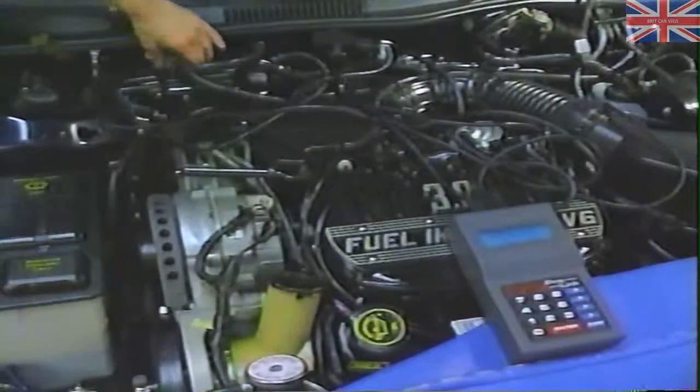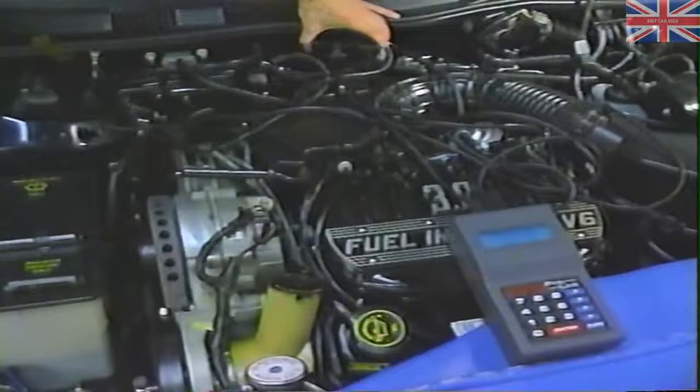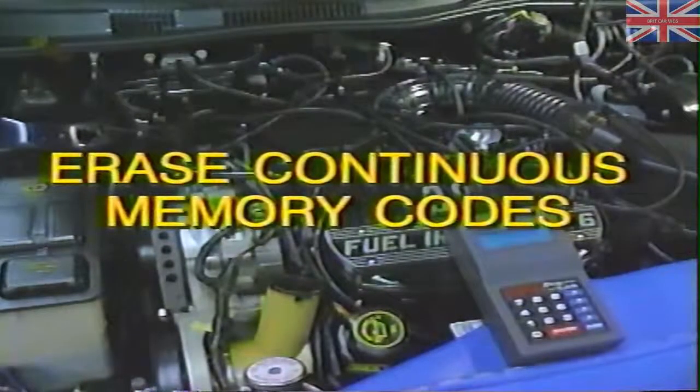Ford refers to this as a wiggle test. You should not perform this test until you have gone through all of the previous test sequences. To perform a continuous running self-test is quite simple. If you remember, we had logged a code 18 while performing the continuous self-test. The first step of the wiggle test is to erase any of the continuous memory codes in the system.